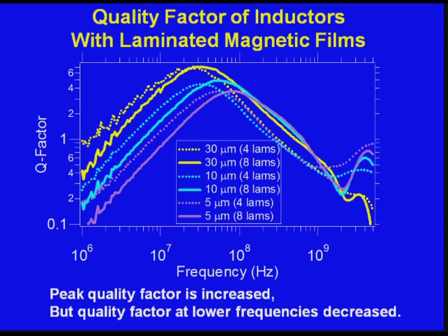Well, if you look at this graph more carefully, at the low frequencies, you'll see maybe an explanation for that. What you see is that the quality factor drops, in this case at 1 megahertz, down to 0.4 or less. What that tells you is there's something dropping. Basically, the inductance is dropping. And that's because you have laminations now in the magnetic via, and that creates gaps. So now the magnetic flux cannot wrap around it so easily. So basically, what this tells you is that you can only do so much lamination before your increase is diminished to something that's not worth doing.